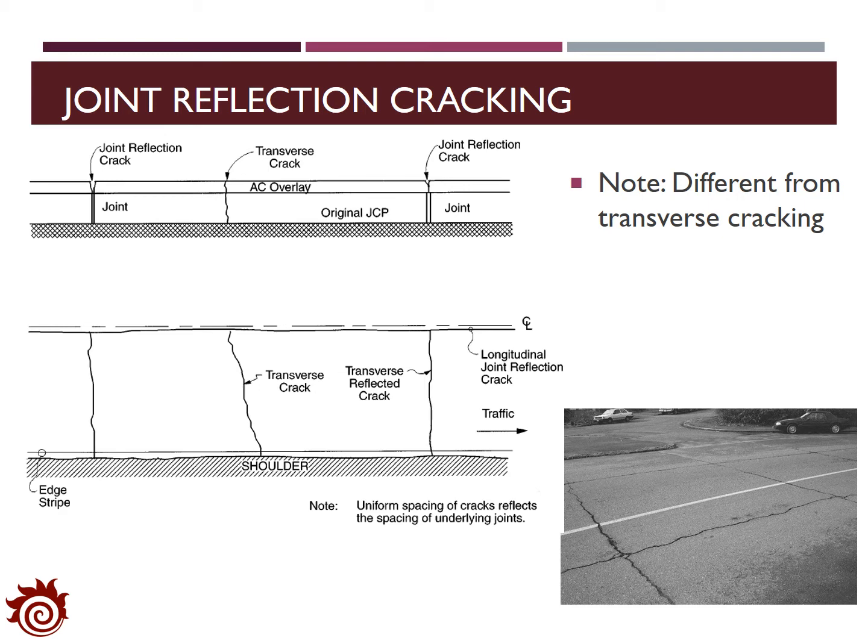joint reflection cracking. And you can see that they are very different from transverse cracks. Joint reflection cracks occur at the joints of two PCC slabs at the bottom, while transverse cracking occurs when the PCC slab at the bottom has some cracks that are transferred to the surface. In reality, you will see some joint reflection cracking. They have very regular patterns, which are very similar to the layout of the PCC slabs on the road.